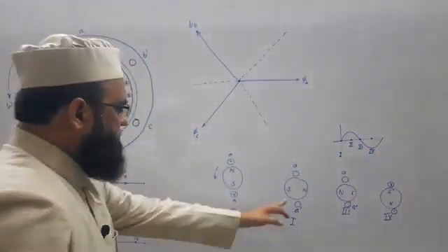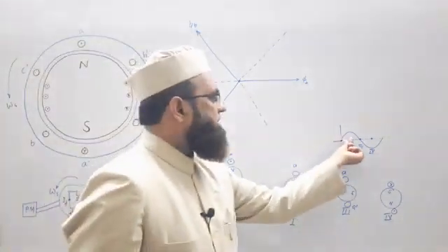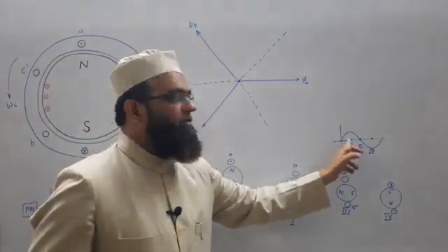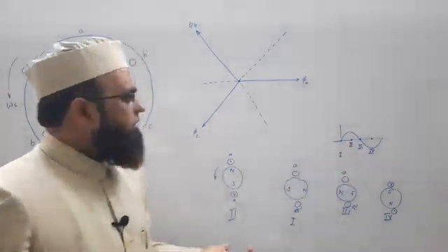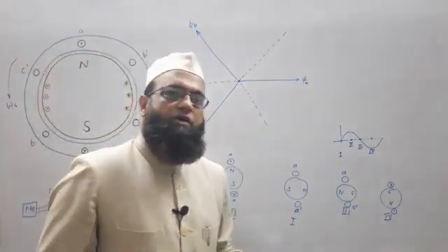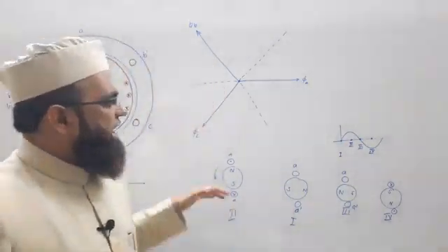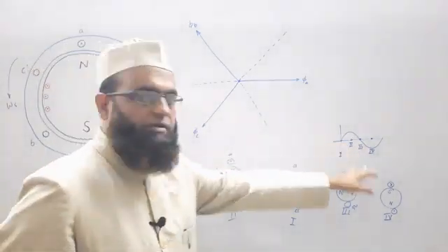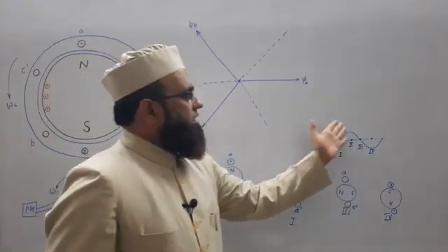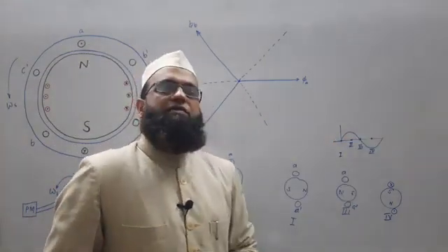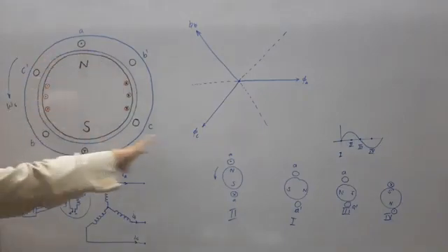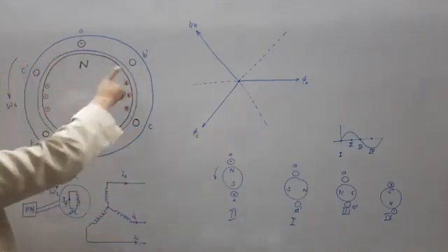In between case 1 and case 2, these 2 moments are there, right? Flux linkage starts from 0 to some maximum value in between, so the corresponding flux linkage will induce EMFs of similar, varying amount, like this. So this way in phase A we can say that a sinusoidal EMF is induced as the rotor rotates, we have talked about one complete rotation, right?